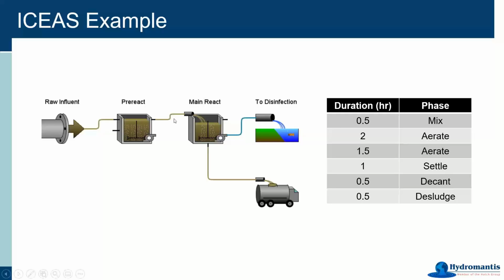Just so that you're familiar with it, we have the influent flow coming in here. This is the overflow connection point. You don't want to connect anything to this because hopefully, if you've got your SBR set up correctly, nothing will ever come out through here. This is the pump for decanting your treated water off the top of the SBR as the level goes down when you're doing the decanting. So this is the treated system. And then down here is where you are going to be doing the desludging, or the wasting, from this particular system as well.